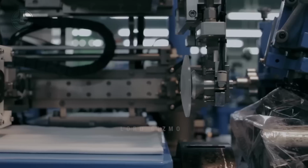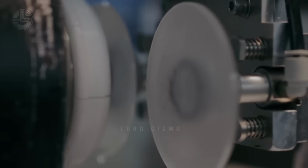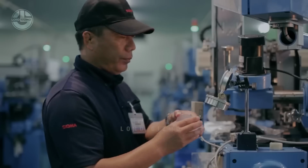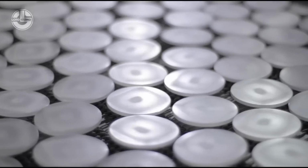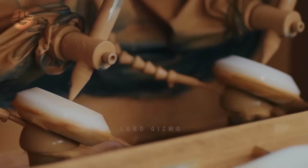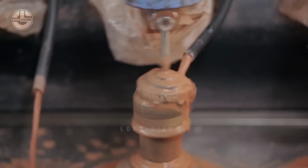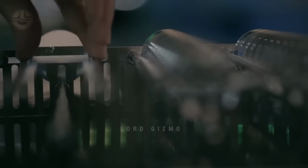In the next stage, precision machining further refines the lens. Then the finely ground lens is fixed in a metal shell for future processing. This locking is called blocking. Now the lens is ready for transformation from opaque white glass into a glossy, transparent lens. To do this, factories use liquid abrasive materials such as graded emery flour and fabricated plates. This polishing process makes the lens surface smooth, transparent, and scratchless.